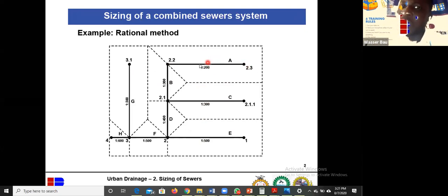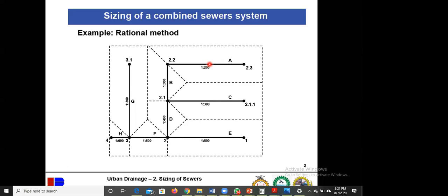So these are the sewer lines being on top, the drain lines being at the bottom. So this line effectively represents two systems. It can represent the sewer system. It can also represent the storm system. Okay, remember what I told us yesterday. One of the differences between the sewer system and the storm system is that the sewer system is usually very small, done with PVC pipe, and it's usually located from 1.2 meters to 1.5 meters below ground level.